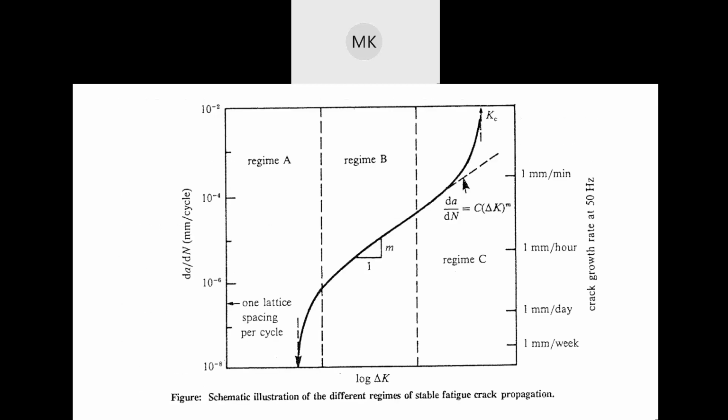So these are the three stages of fatigue. This is stage one, when you're going to have a small crack initiated, but that is the major crack in that stress field or in that plane. So that's what is generated in stage one. The amount of crack growth that you're going to see is at the nanometer level, or rather hundreds of picometers, so 10 to the power minus 10 meters. So it's going to be really, really small when you see it.